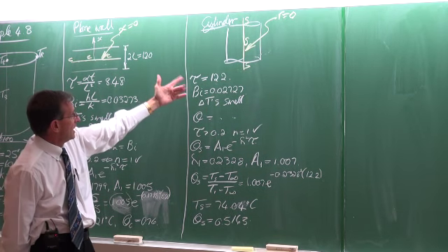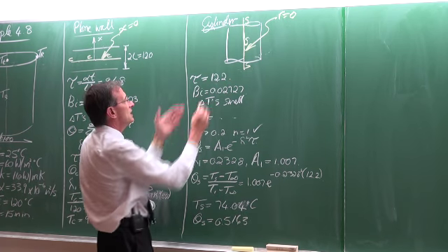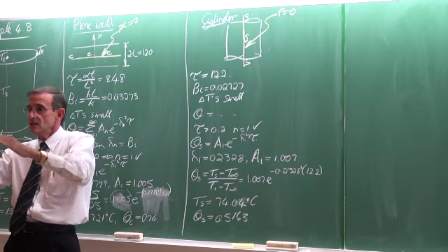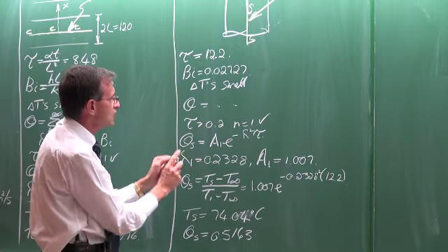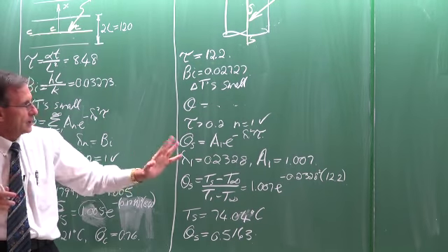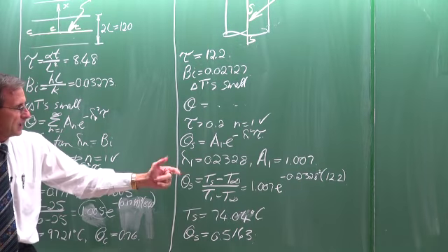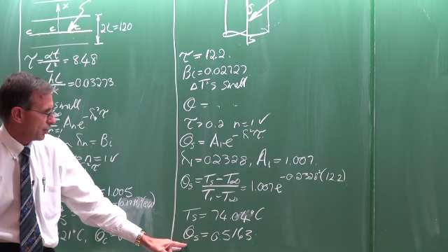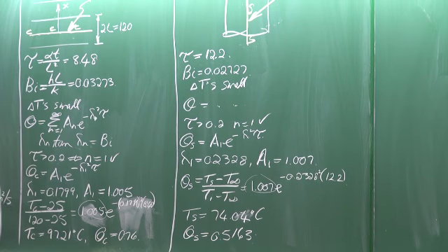Okay. So again, we calculate the non-dimensionalized time. It is 12.2, the Biot number. The Biot number is small, so the gradients of temperature inside should be small. We go through the process with the equations. We only need to look at n equal 1. There's the equation. Get lambda and A. Calculate the non-dimensionalized temperature, from which we can calculate the temperature. Again, yesterday I forgot to put in that value with that one also, and that is where we stopped.